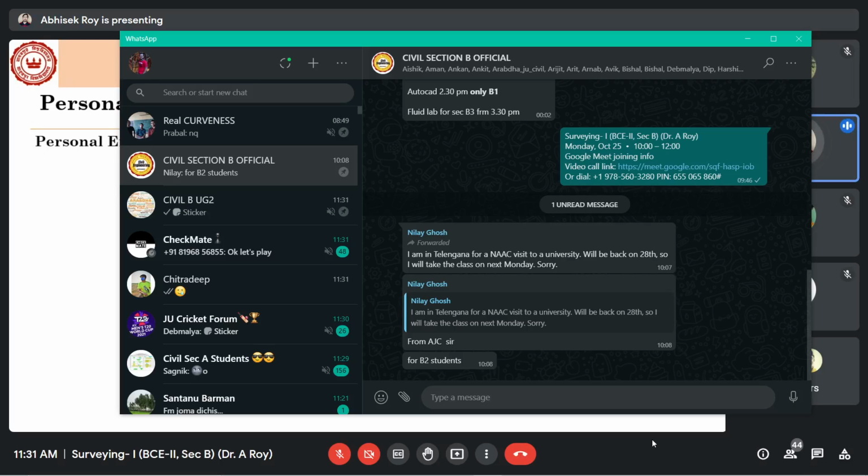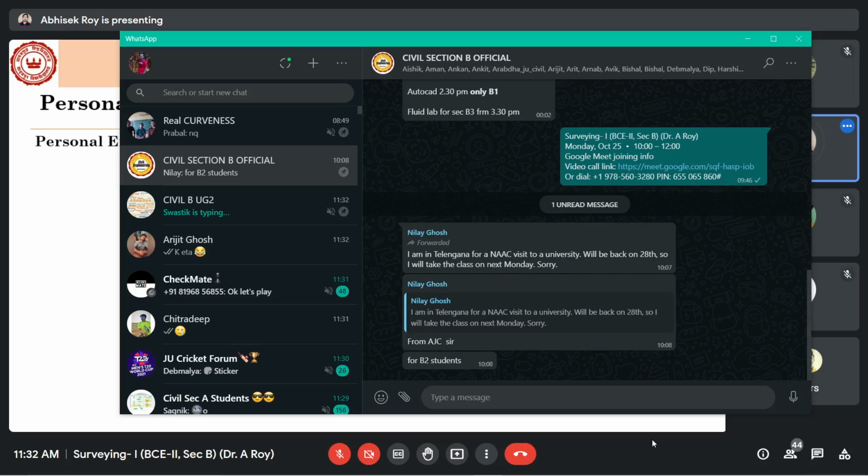and that is slip. Now this sort of error is very hard to remove, so obviously you have to be very serious while taking the measurements. You have to be very cautious in taking the measurements. Okay, because suppose you are taking the measurements at P and Q and you have bisected P, and suppose your lower main screw is not properly tightened, so now if there is any slip, P will change to P dashed, right? So this sort of error will be there, so that's why slip should be avoided. Okay, so you have to work properly.